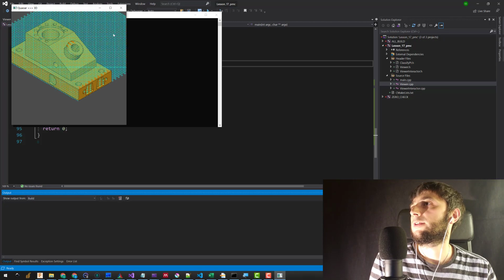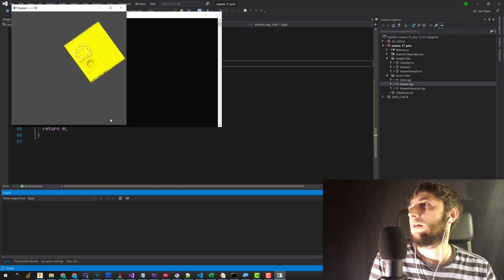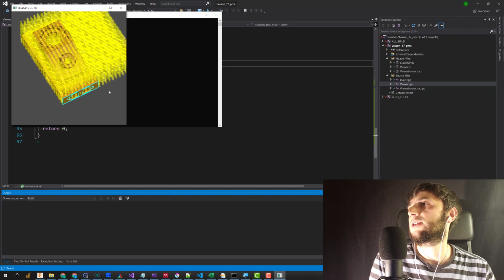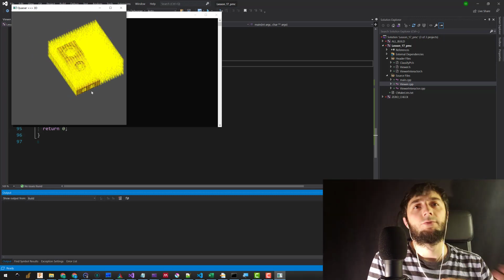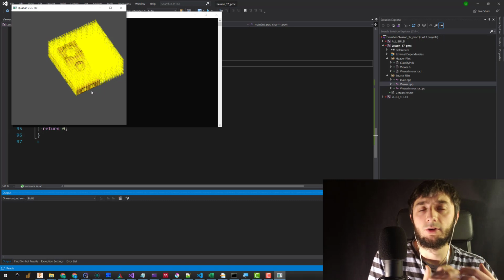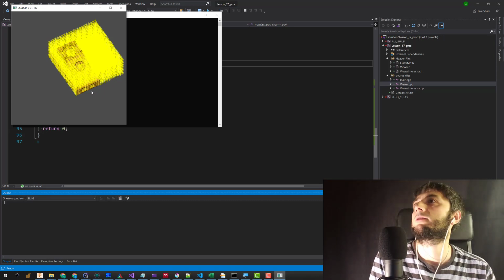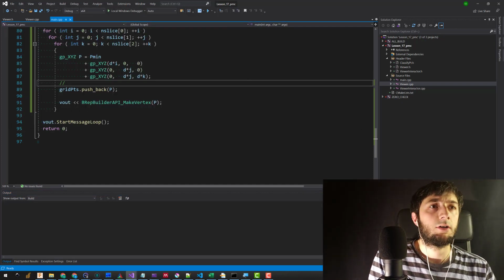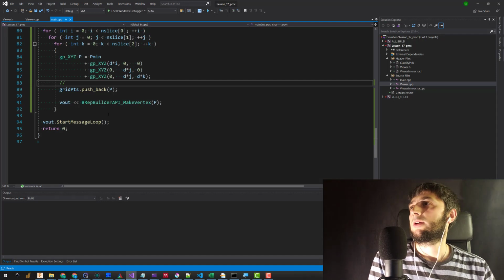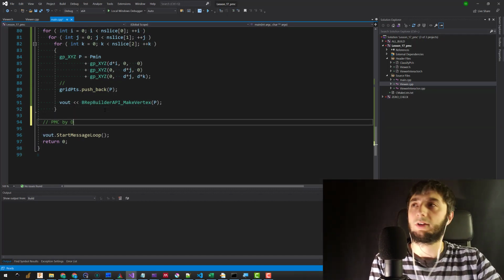You see that we have this grid of points. Some of the points lie inside our shape, some of our points lie outside the shape. And now we want to classify them and maybe to keep in the scene only those points which belong to the solid, which belong to the interior of our solid. So let's close it for now and see how we can classify a single point. So now we are going to do this point membership classification by Open Cascade.